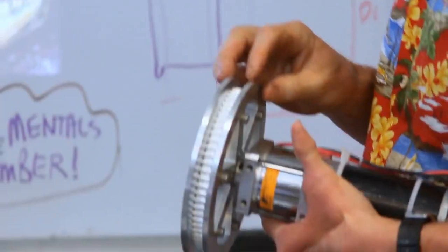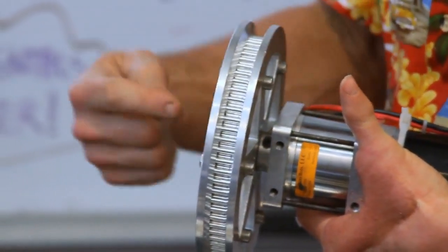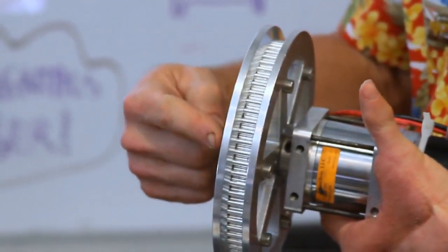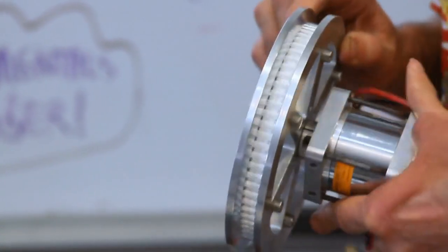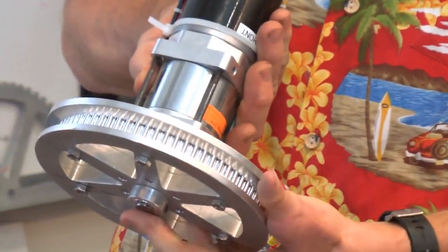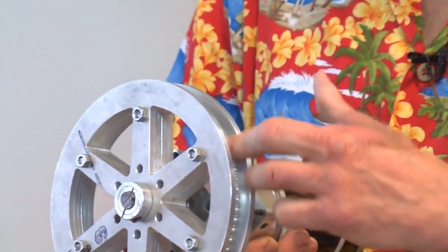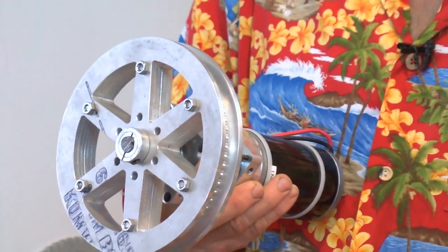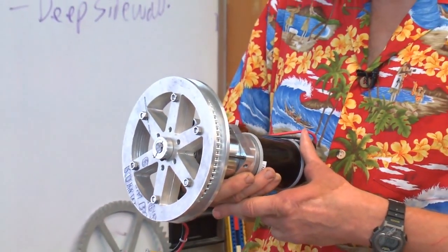If you look real closely, you'll see this is two parts that are identical and they're bolted together. So this was actually off a First Robotics Team robot, the Bishop Brady robotics team in Concord, New Hampshire. And they've made their robots for several years like this with these belted tracks. Never came off, ever. Maybe once actually when the belt got so worn it was stretched way out, but nominally never came off. Much higher reliability than wheels even.